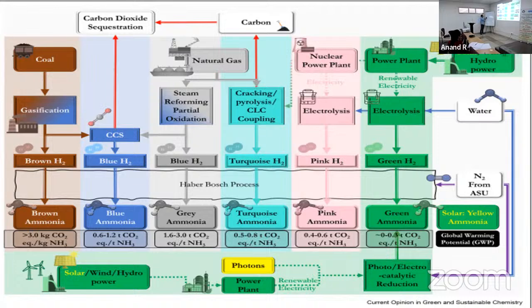So 1 kg hydrogen production needs this much quantity of CO2. Here 2 kg CO2 equivalent, here 2 kg equivalent. You can add them up, and then 10 kg CO2 equivalent for producing 1 kg hydrogen. You have to derive it like that. This is for global warming. Similarly, you have to think about the energy aspect. For producing 1 kilowatt hour of electricity, how much energy is needed as input?